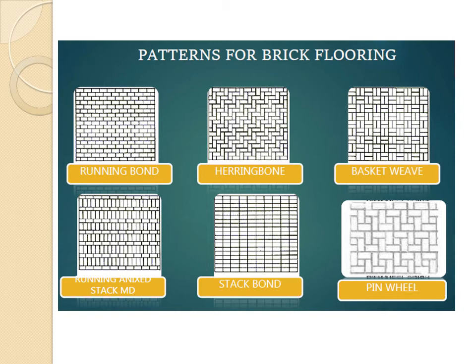These are the hash patterns basically which indicate the brick. And if you could see these patterns, these are particular kinds of bonding which are made out of brick for flooring. In the same way, next basket weaving bond. You can see the pattern is similar to what you find on a basket, which is a bag, right?